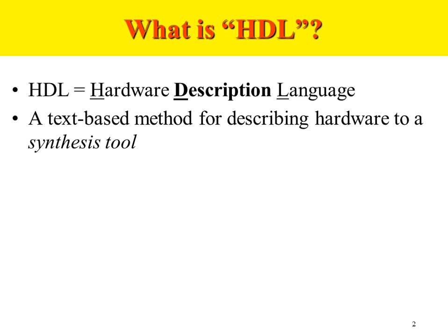A synthesis tool is basically a synthesis software, where the design entry of the hardware design is in this language called Verilog. Verilog and VHDL are called HDLs, hardware description languages. So what we do is we describe the hardware, not program the hardware in a sense. We describe the hardware to the synthesis tool, which will then convert that Verilog language to a gate level netlist.